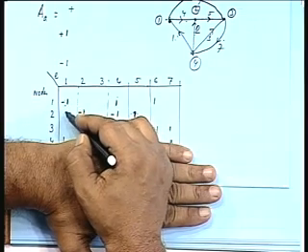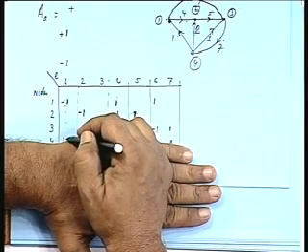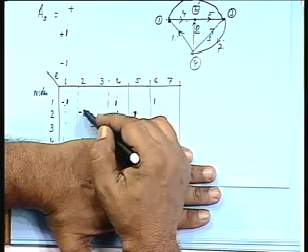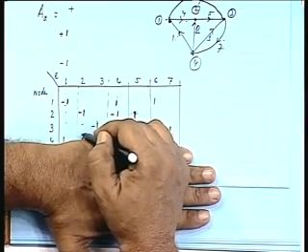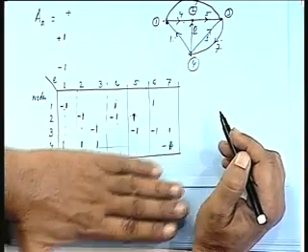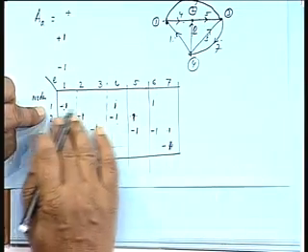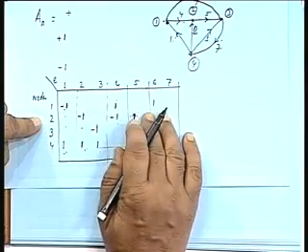When you have addition of these elements equal to 0, then this is not an independent equation. Without that I can fill it up. Wherever there is -1, the rest are all 0, so it has to be +1, because total sum has to be 0. So any one of them, you say remove row 2.